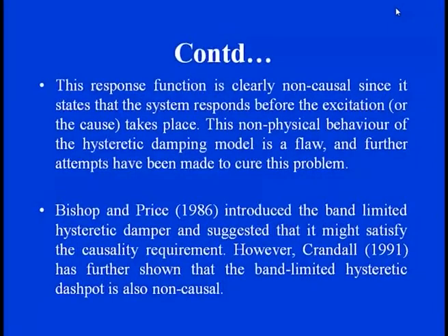So this response function, which is clearly showing the impulse part, is very clearly non-causal, since it states that the system responds before the excitation or any cause basically takes place. And the non-physical behavior of this hysteresis damping model is a flaw, and further attempts need to be made to rectify this problem. So this flaw means it cannot be a perfect representation.